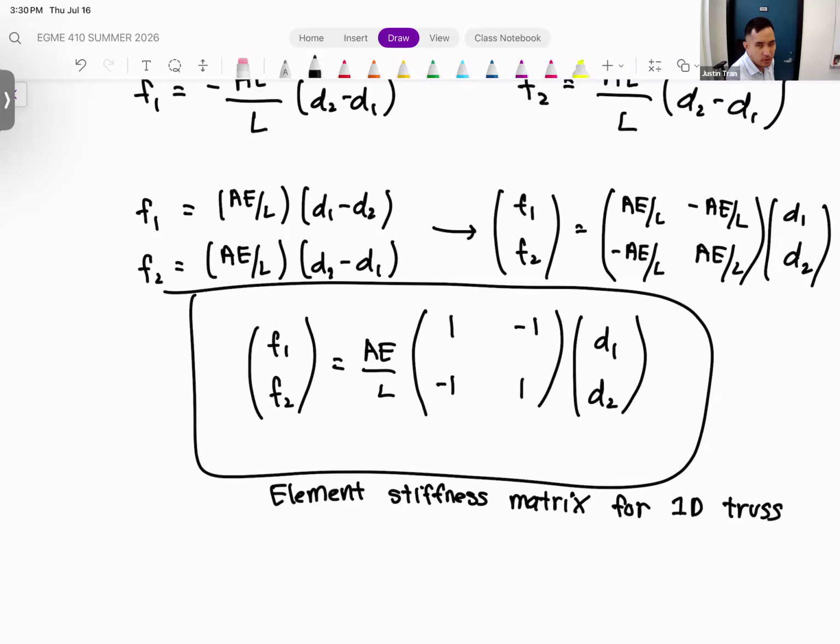And in fact, most of the time people can consider them to be one type of element, which makes sense because the way that a truss bar deforms, so it can only deform in tension and compression, is exactly the same way that a spring can deform. A spring can only be compressed and extended, at least in terms of its primary mode. I know you can take a spring and bend it, but typically, if you're using a spring for its intended purpose, it's only going to be in tension and compression, which is kind of what we're doing.